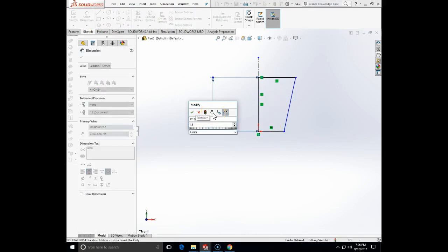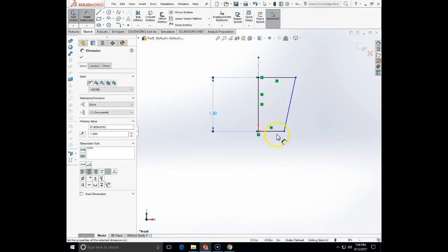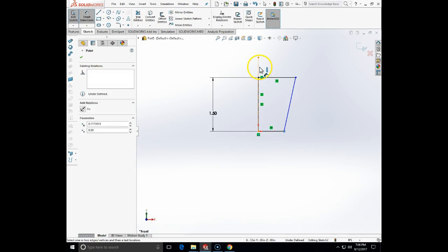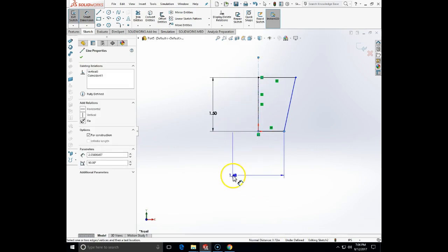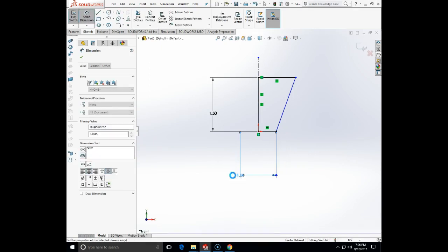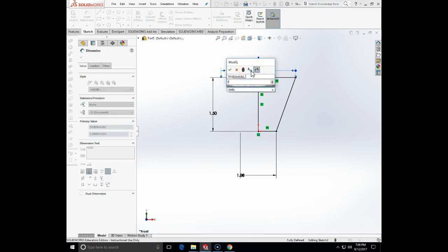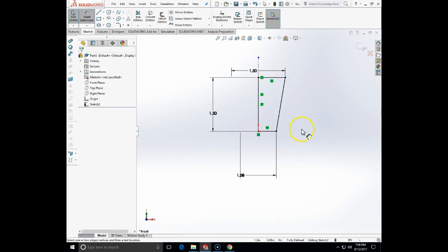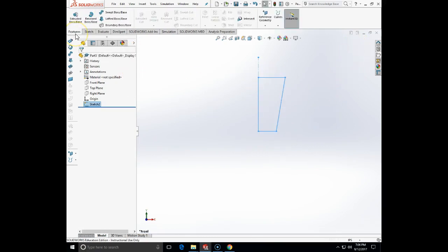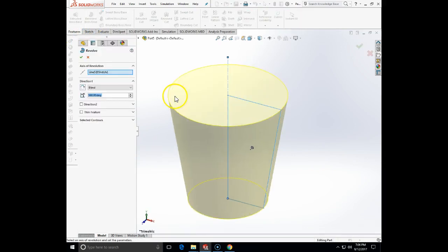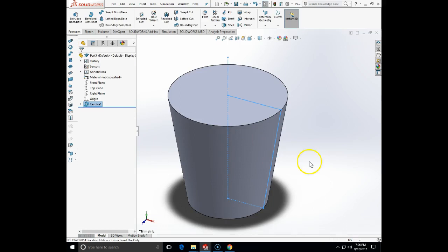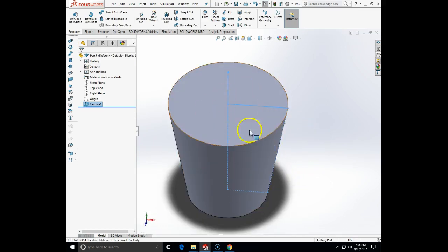Like in height I will put it at 1.5 inch. The bottom diameter I'm going to put at like 1 inch, and the top diameter maybe 1.5. So that will be the outline of the contour. Now, what I'm going to do is revolve and create something like this. You see that I intentionally made it full. I did not hollow it, I will use the shell command to hollow this.